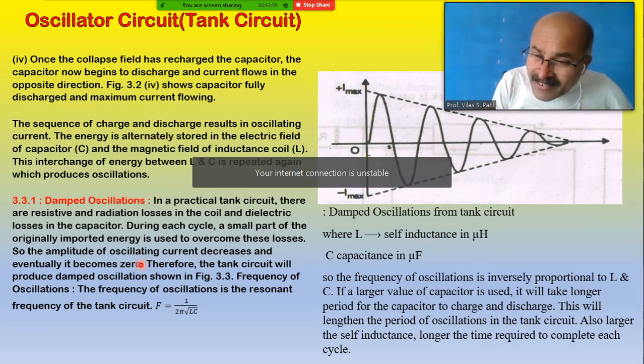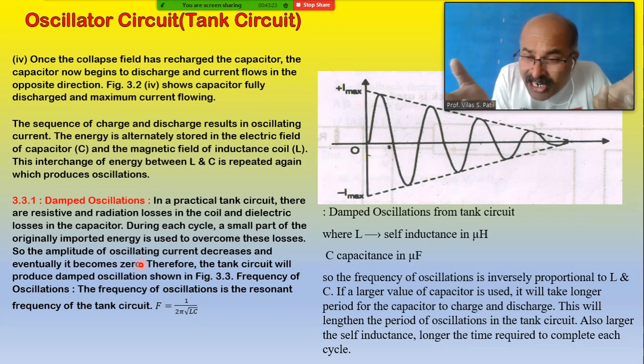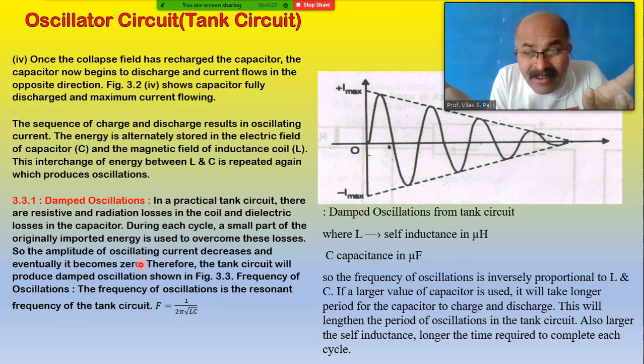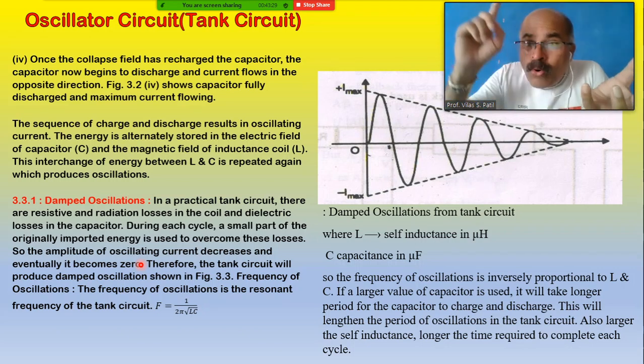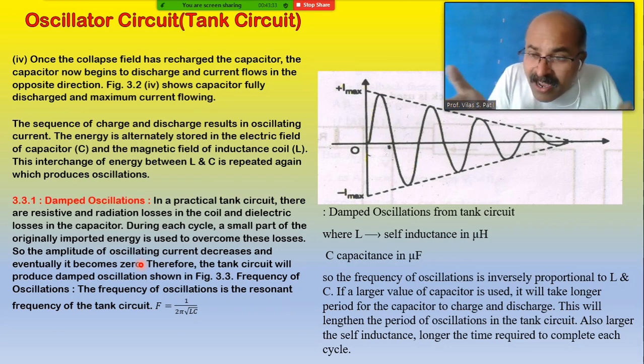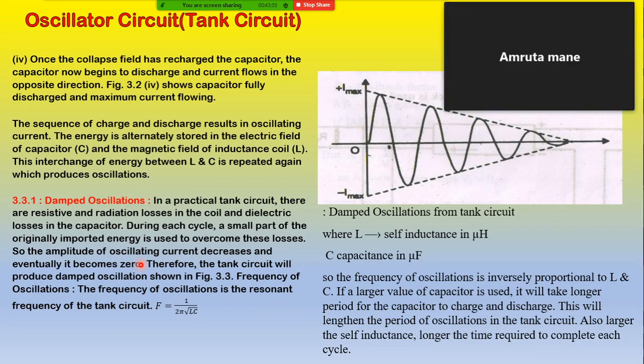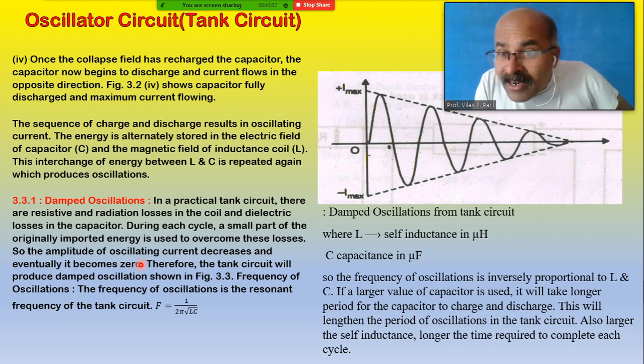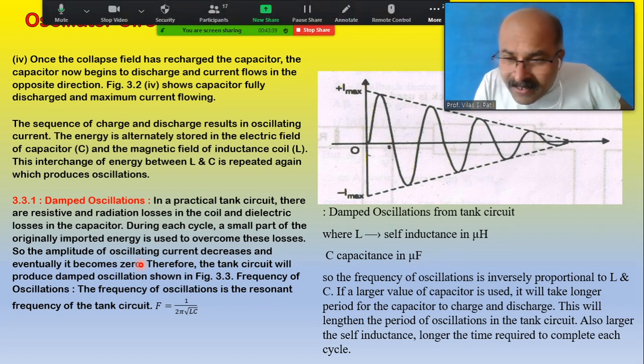Why is it losing amplitude? Due to the interconversion of energy between the inductance and the capacitor, due to the ohmic losses inside the inductance, and due to the electrostatic losses across the capacitor.